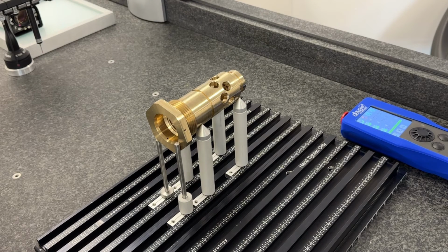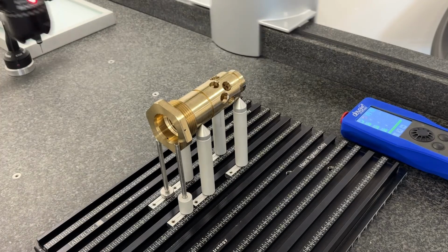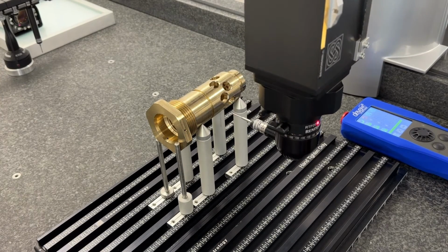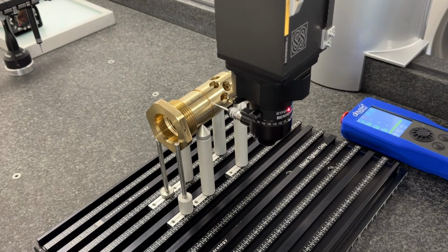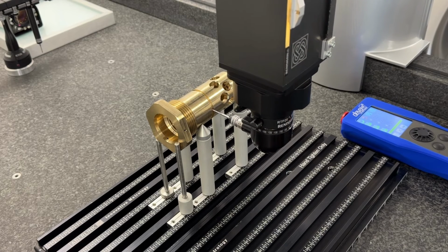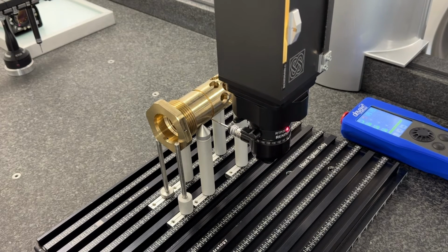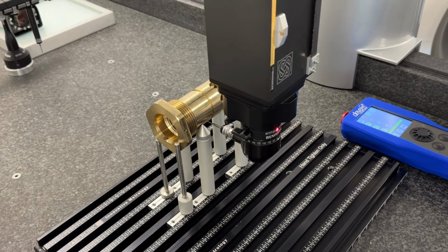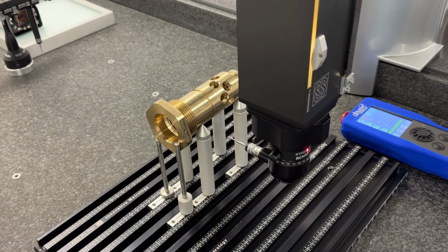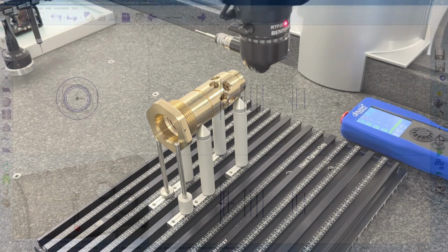So in this particular case, you can see I've gone for my preferred method of using A90 B0 and A90 B-180. Getting at it from 2 angles, this means you only need 2 probe angles and you're going to get the full sweep around the part. You obviously need good fixturing like this to be able to access the underside of the part as well. But if you're ever trying to measure this and you can only measure half of it because you're measuring at A0, B0, that will skew the results. So just bear that in mind.